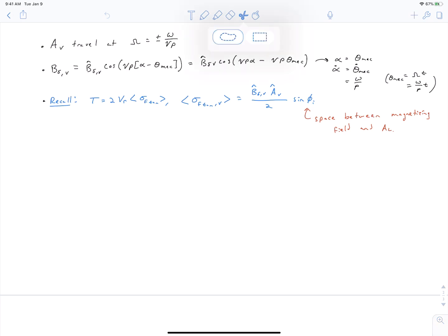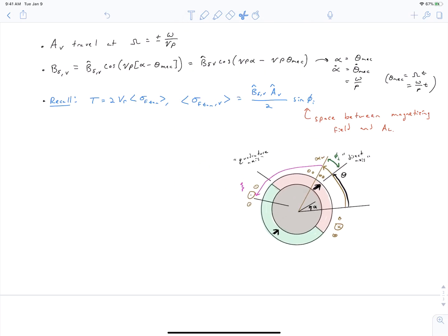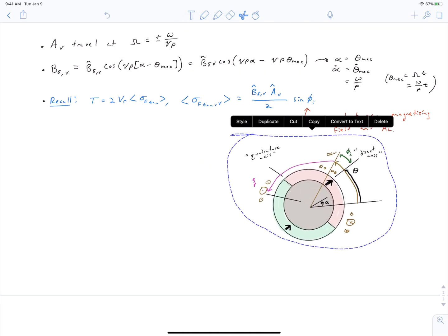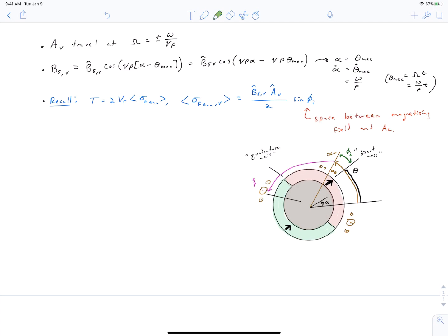And so if I paste in our diagram that we drew from our machine design sizing unit, we can look at the physical interpretation of all of this. So here we've got our rotor's position at angle theta, which is the distance to the North Pole. And then we've drawn on here our equivalent linear current linkage. And the distance between that winding's axis, that equivalent linear current linkage axis, and the North Pole of our rotor is this phi I value.